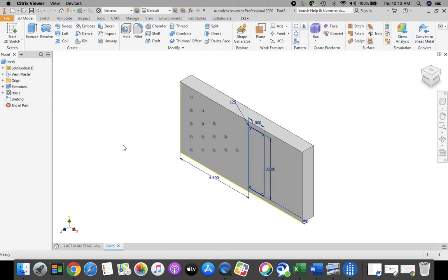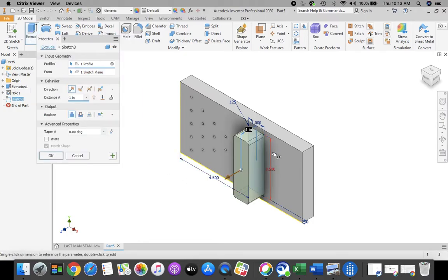And now we're going to extrude that into a pocket. So I'm going to come up to my ribbon bar and select extrude. It should automatically pick up on that area that we just drew. However, it doesn't. You just need to put your mouse over that rectangle and click to select it. Now this is getting extruded the wrong direction, so I want to turn this from a join to a cut, so select this second button. That's going to cut it.